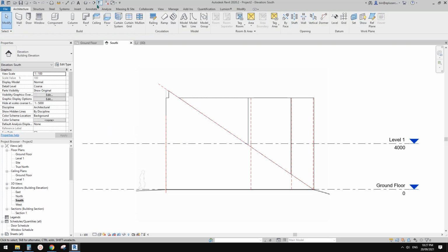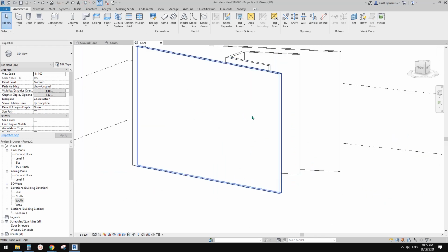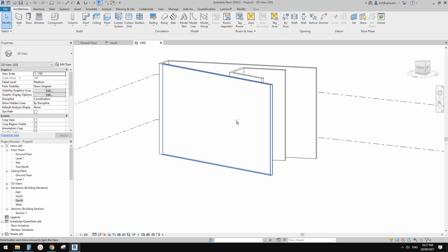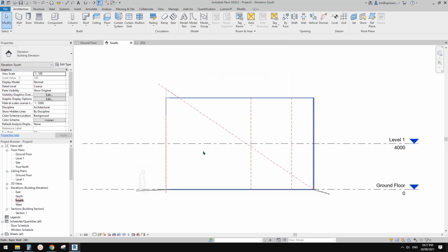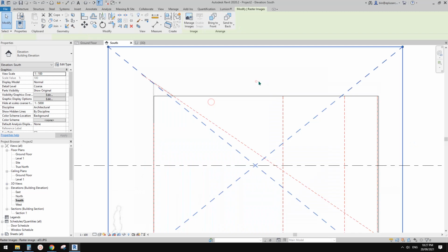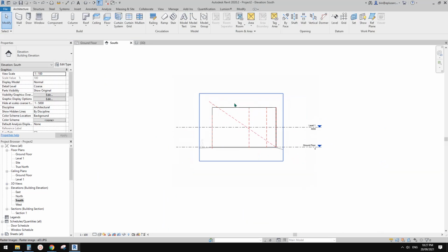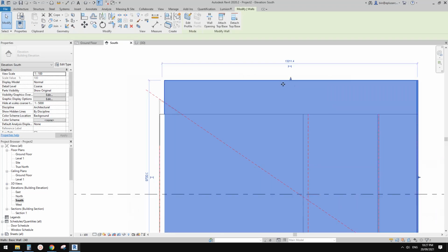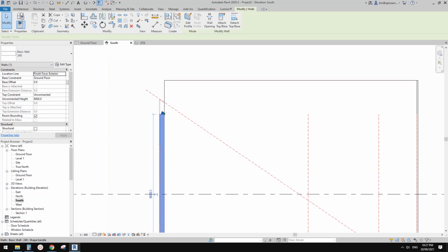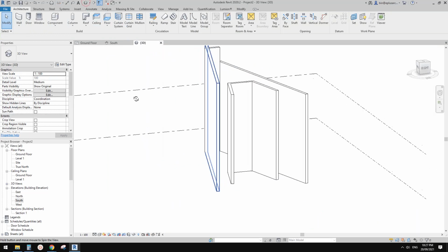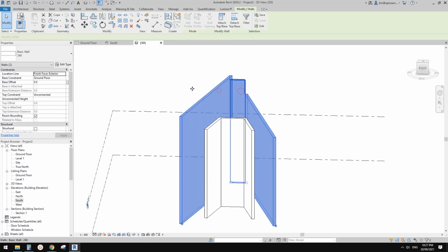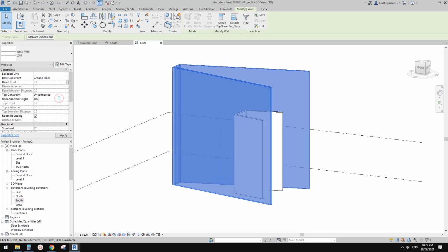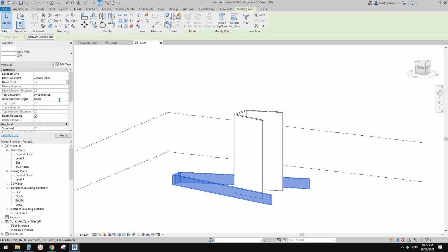The other way, let's just go back. Okay, Control Z and Control Z. Yep, all good. The other way is you can just cut them using a void, but before that, let me just pin this image. Make sure this wall is tall enough to reach this. It looks like this one needs to go up as well, and this one. So maybe I'll just make them 12 meters high, that's tall enough, maybe 10. Oh, not 11, sorry. 10.